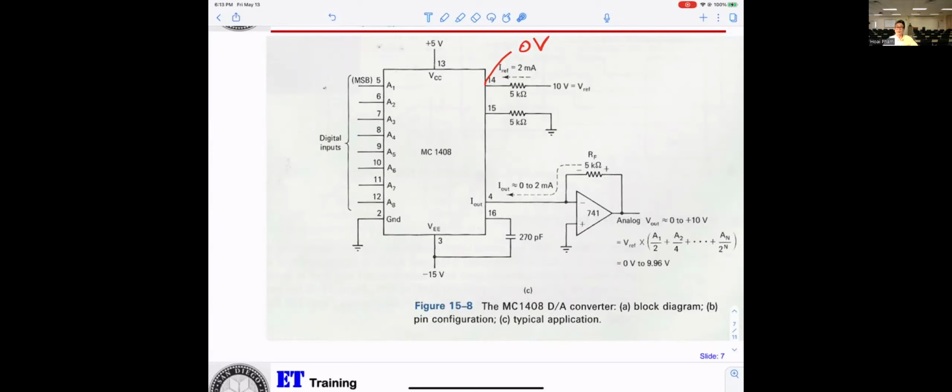Yeah, that will be applied 10 volts. Technically, when we use the lab, you can see how we get 10. So technically, the 5K is going to drop it to 0. But if you have backfeed from pin 14, your voltage regulator is probably fried, right?